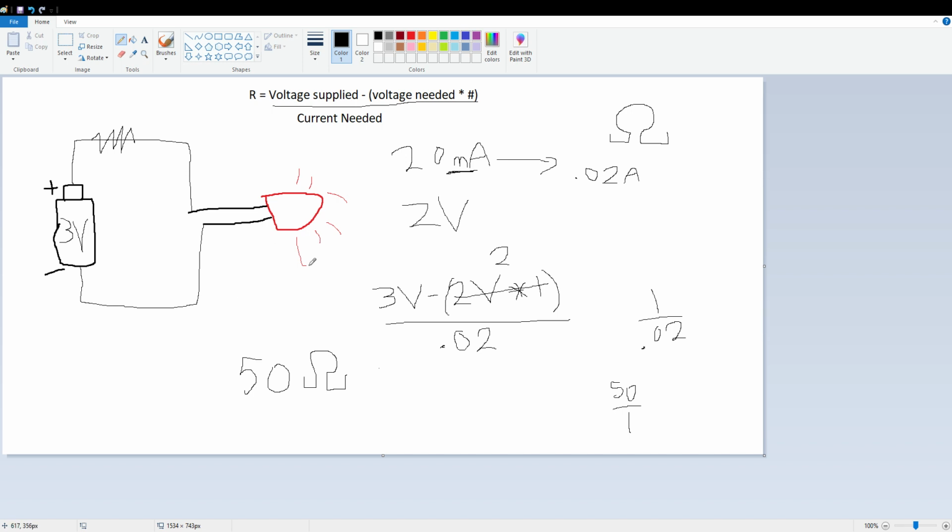Because I can tell you, my first thing I ever did when I was working on an electronics project was take a 3-volt battery and go, oh, this is an LED, I should just wire it all together. And poof, the LED just instantly burnt out. And I didn't have an LED after that. So something to keep in mind, if you're following a tutorial, read the steps. Don't skip steps with this, because this is how you end up damaging equipment that's not already protected.